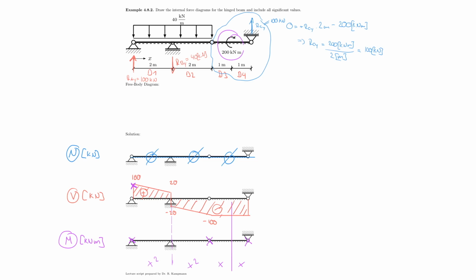So let us draw the slope upwards, upwards, upwards, and then I have to have a slope of 0 there. Actually, it's funny, there's an immediate kink there because it jumps to 0, the shear force diagram. But once again, you see here I have a higher value of slope and a positive slope. By the way, don't be fooled by this going down. It is all positive, positive, positive. So therefore, I need to have a positive slope throughout.